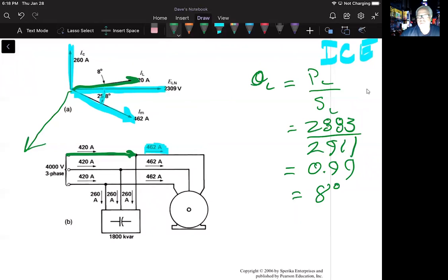That is a big mind shift for us, as up to this point, we've focused on tracing currents, going through elements, but let me say that one more time. The impedance values of devices such as resistors, motors, capacitors seldom appear on a nameplate. This is to be expected because most industrial loads that involve motors, furnaces, lights, and so on, are seldom described in terms of resistance or reactance. They're represented by devices that draw a given amount of power at a given power factor. And we can figure out from that information what's going on.